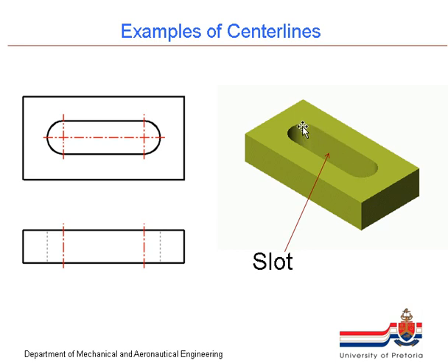This feature over here, it's basically two circular holes with the material in between removed. That is called a slot. A slot is drawn from the one side, we can see the two circles. And from the other side, if we view this from the bottom, in this view we will only see that outside edge's hidden detail and the one on the right hidden detail. We will not show the hidden detail for the tangent portion where the arc goes into a flat plane.